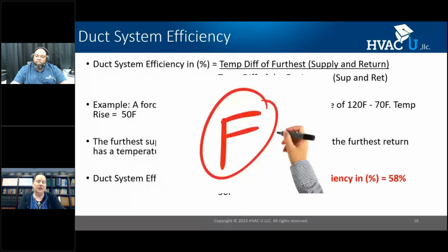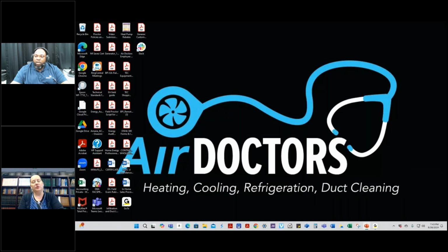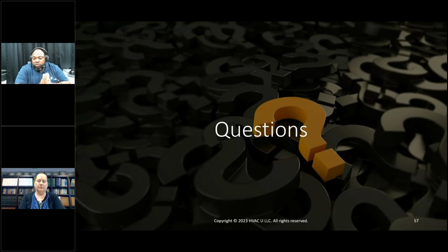How do you get a homeowner to pay for the pressure pan and blower door test? That's a very good question. These different tests are typically going to be used when you're trying to evaluate a problem. In my experience, if the customer is experiencing an issue and they really want to solve it, and you have the data to show the customer that you can solve it, I've always started with measuring static pressure and airflow.